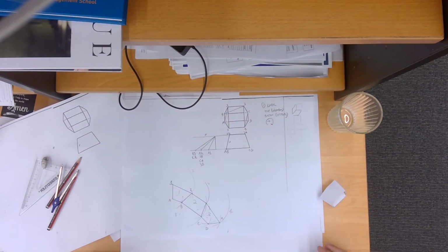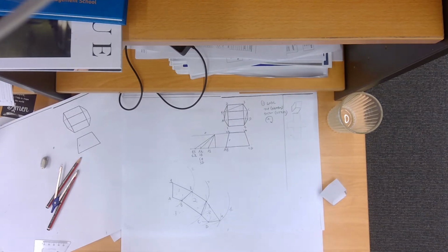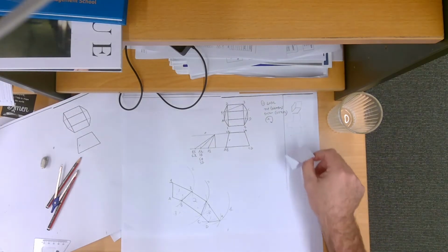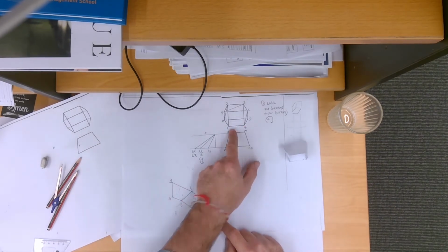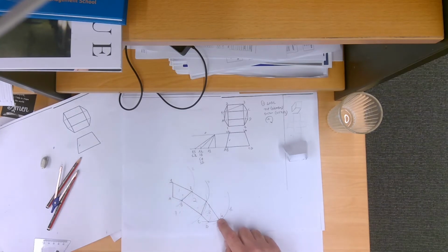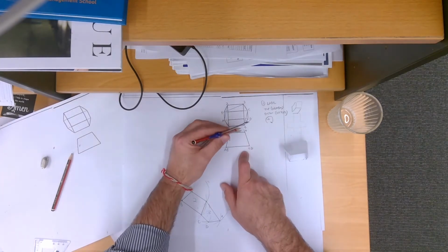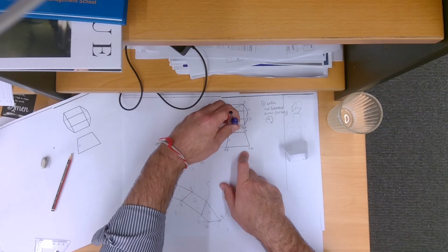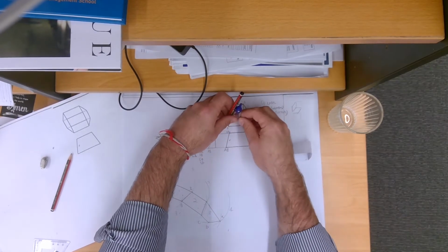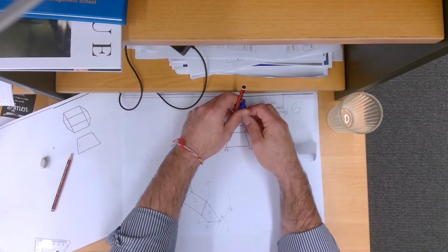Okay, last bit, we ran off the page, so I've added a bit of paper to the page. Hopefully this will help. So we just need to go from 4, you guessed it, back to 1, which is our seam. Okay, so we've only got 3 faces, so we need to do that last face. 1 to 4, as you can see, is a horizontal in this view, so it's a real length here. So we need to get that length down here, 1 to 4.